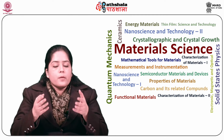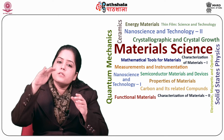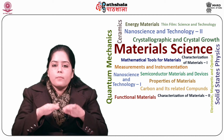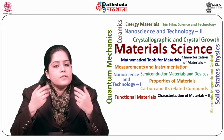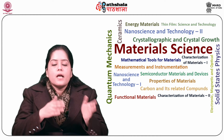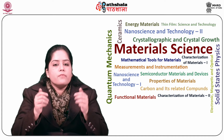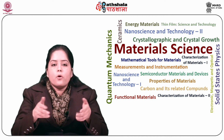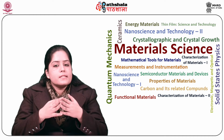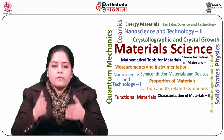Stacked transistor approach. Now stack a p-channel device on the top of the n-channel device. The two can share a common gate electrode. This structure can result in very dense static and dynamic RAM cells because it eliminates the conventional device isolation problems. So a pair of these devices forms a static memory cell that resembles the static RAM.